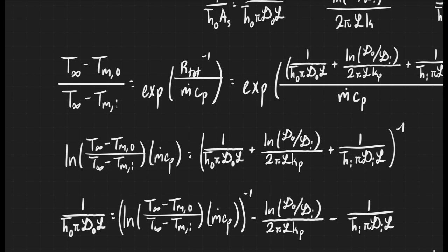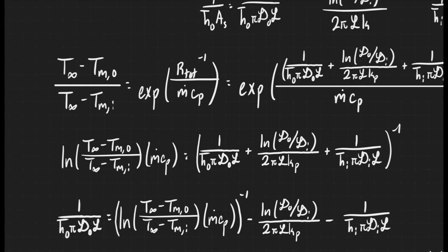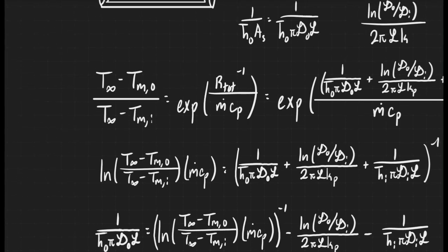This gets pretty hairy with some math, but it's intuitive in the sense that as my thermal resistance is lower, my outlet mean temperature is going to get warmer because that means I have less resistance, and so more heat would be pulled from the environment.